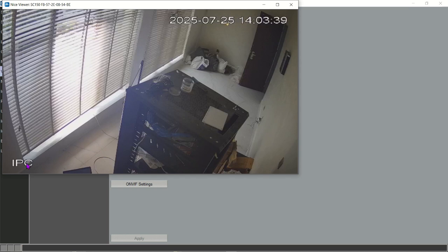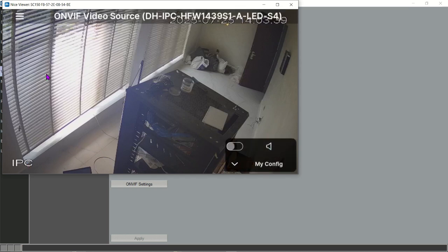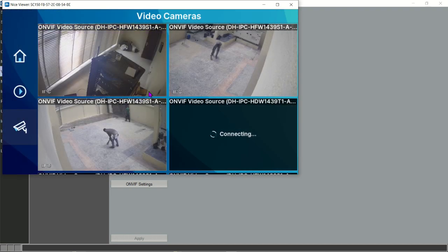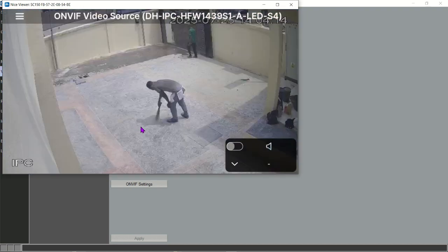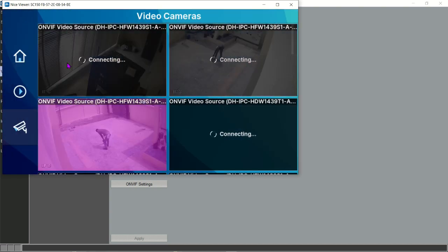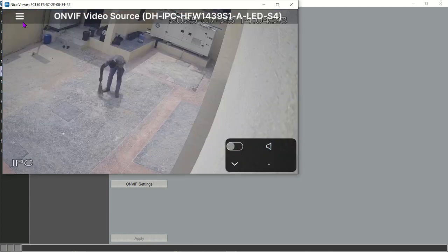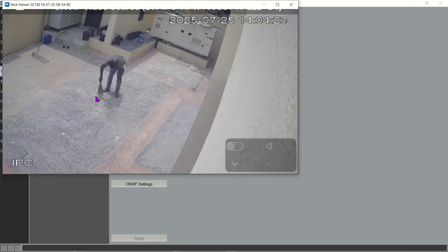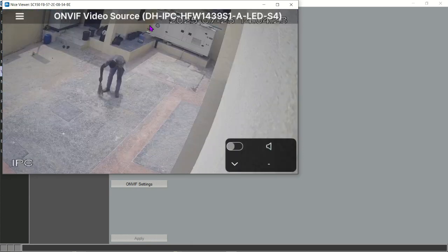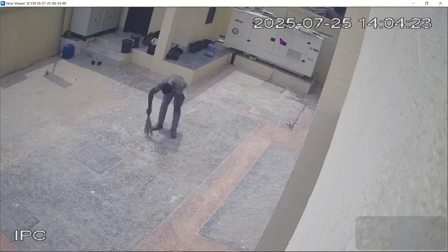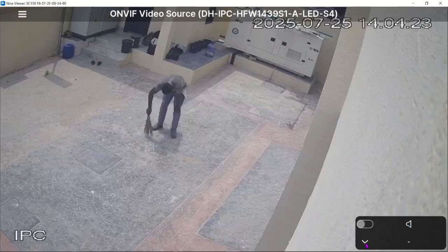You have to differentiate which is the 265 or 256, and which is which resolution. Now, the reason why this stuff hooked means that the resolution is too high. So you have to reduce the resolution so that on the NVR, it's going to play well. But for the NICE, you have to reduce the resolution and reduce the compression to work well.